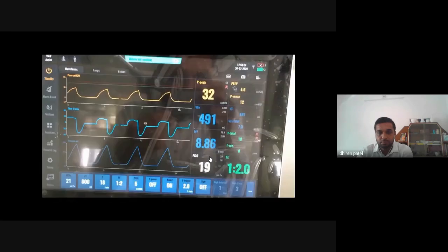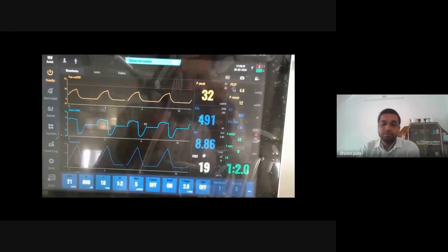So for this circuit, we have to understand one thing. We have to accommodate two people on one ventilator. Physically they have the same kind of lung structure inside, so the volume of air is going to be divided 50-50. So we have to double the volume rate in the machine, so they can each get the same volume. And the United States Food and Drug Administration approved this circuit for use in this emergency.